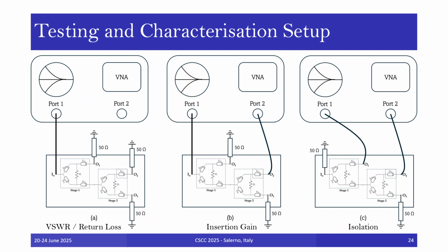Before the measurements were carried out, a two-port through-reflection-line calibration over the frequency range of interest was carried out. This ensured that the reference planes for the measurements were taken at the end of the test cables, and that the cable and the connector effects were removed.